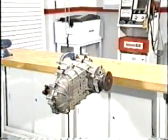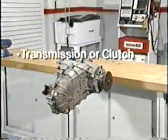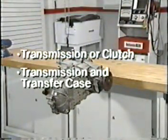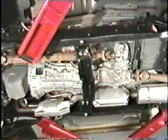Our final comments on transmission noise diagnosis deal with the transfer case. In 4x4 vehicles, you'll be faced not only with isolating noise concerns to either the transmission or clutch, but also between transmission and transfer case. When examining the transfer case for a bearing or gear noise, consider all the facts.